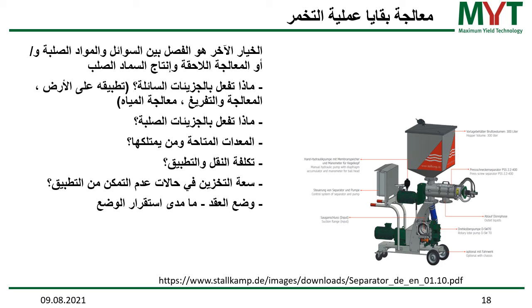Digestate handling, an option here is also solid-liquid separation. So here you can actually separate out solids in order to condition your digestate for further application on agricultural land, for instance, or in order to condition solid fraction for post-composting process. So this unit you can see here is a very simple solid liquid separator for manures, for instance.